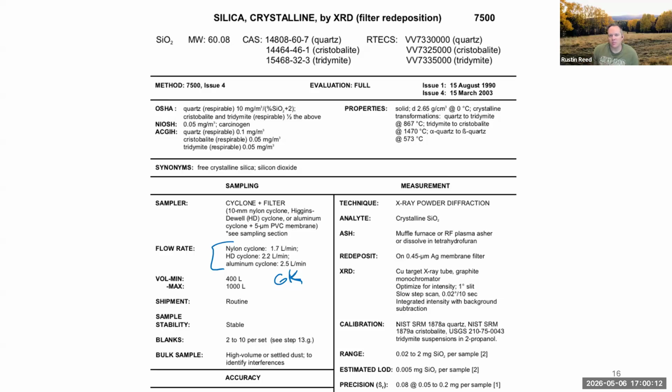So there may be more of a shift towards 8 liters per minute, whether it's a short task or concentrations are just very low. We could ramp up our flow rate to get a detectable sample. So it's something I would definitely consider. I'm considering it right now. I just have to do some research on what sort of pump can do 8 liters per minute. Those are all really great questions.